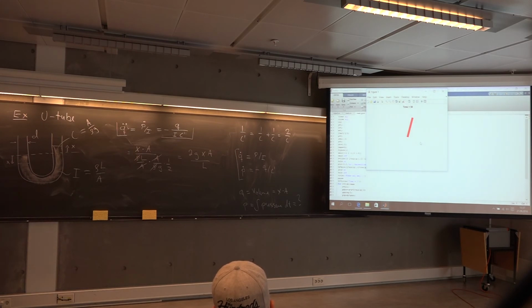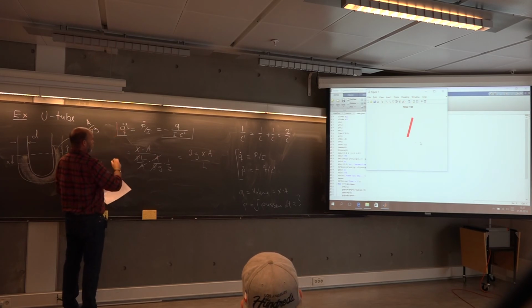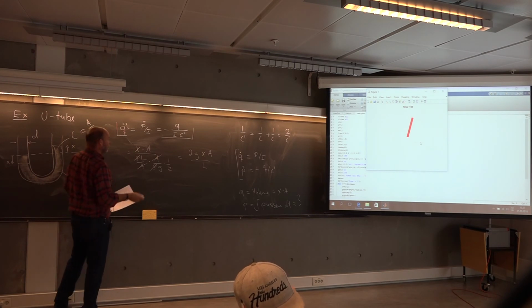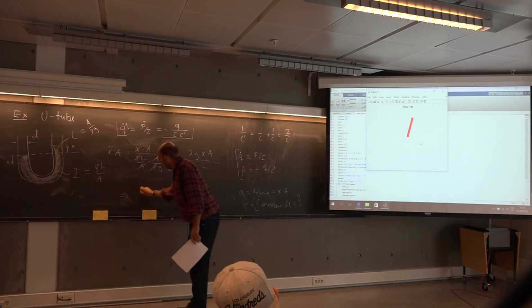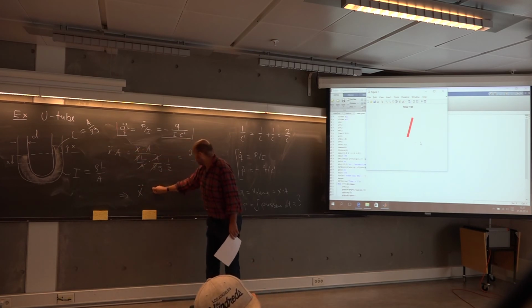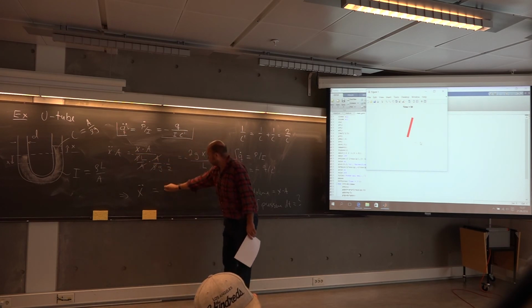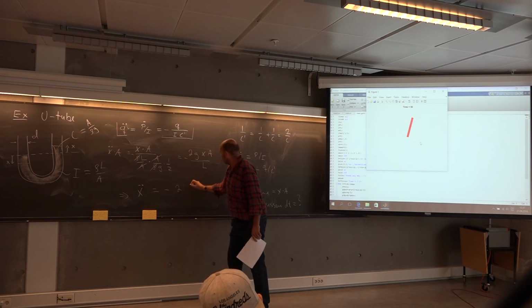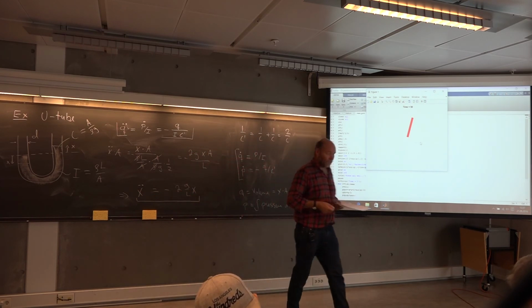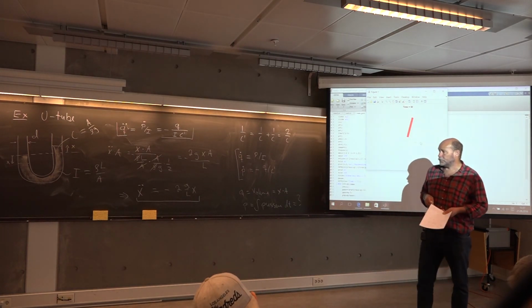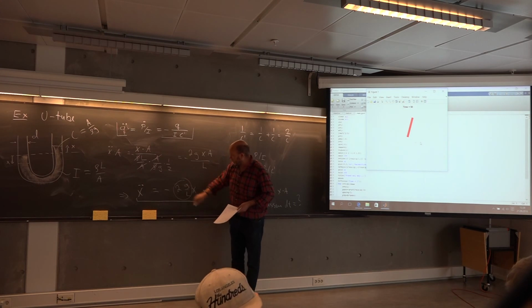If you want to use x instead of Q here, then this one will now be the volume double derivative, so it's x double dot multiplied with area. So only looking at x, I have dropped the minus somewhere. Should be negative: x double dot equals minus 2 times g over L times x. So this is the equation. And yes, it's a linear equation describing a harmonic oscillation. And the natural frequency is just the square root of this part.